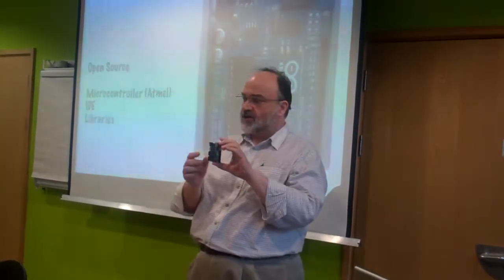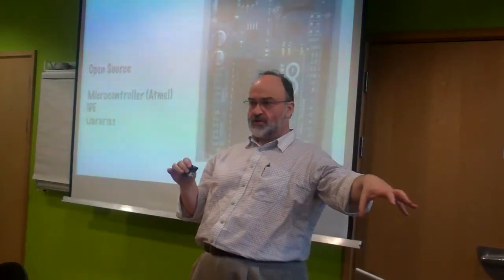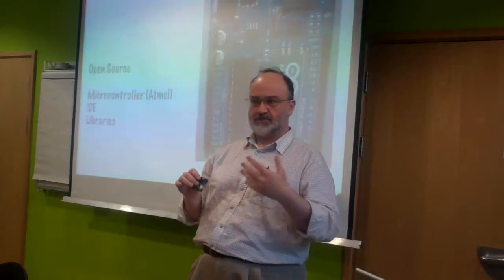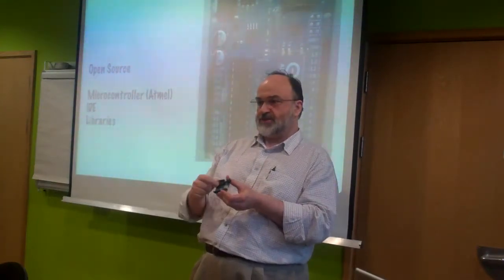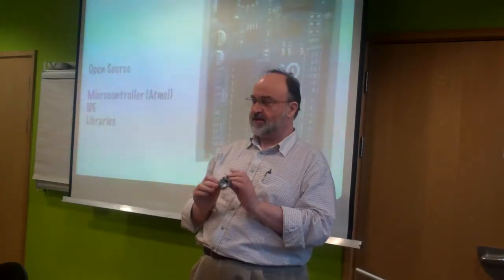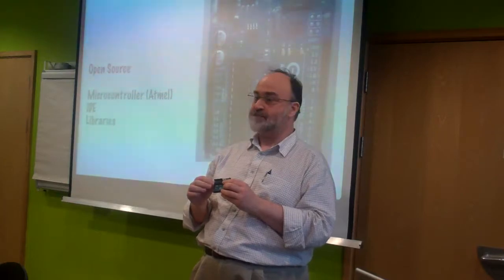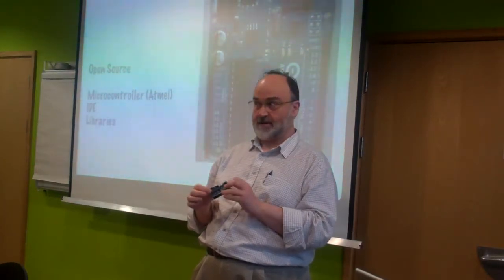So Arduino, that's one of these little microcontrollers, and it basically plugs in over a USB cable. You run your compiler on your host PC, which could be Linux, Mac or Windows, and the actual program runs on the chip. This is a fairly modern one, and it has 32k bytes of program memory and 2k bytes of RAM.